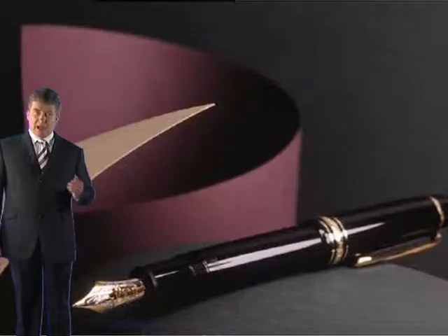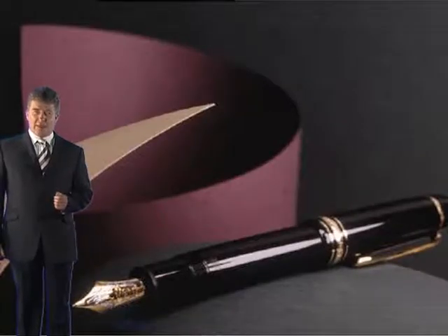And these are the problems that you may expect. And again, you must ensure that you take into account this deflection. Now, there has been a lot of work carried out, and it has shown that the deflection of a smoke curtain and the flow of hot gases through gaps in it can be directly related to the hot gas layer contained by this curtain. So the actual temperature of the gases.